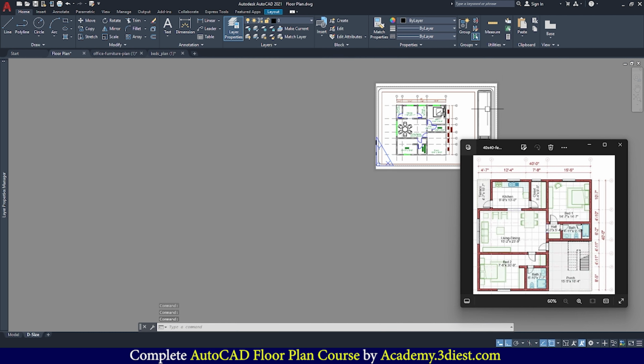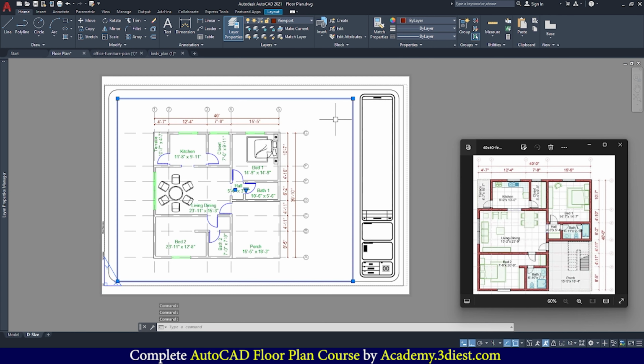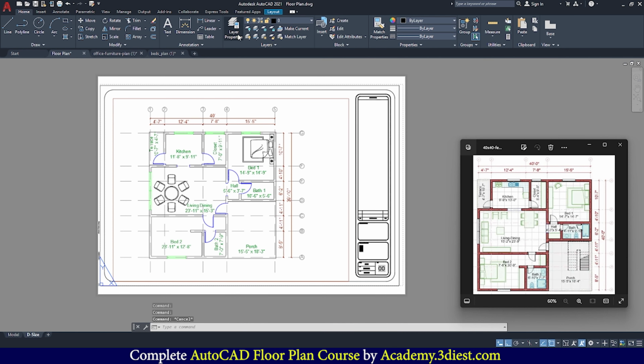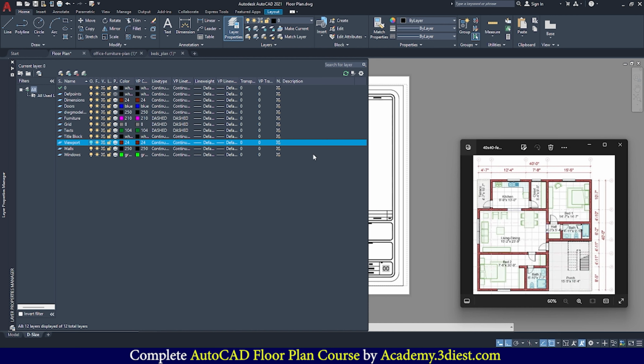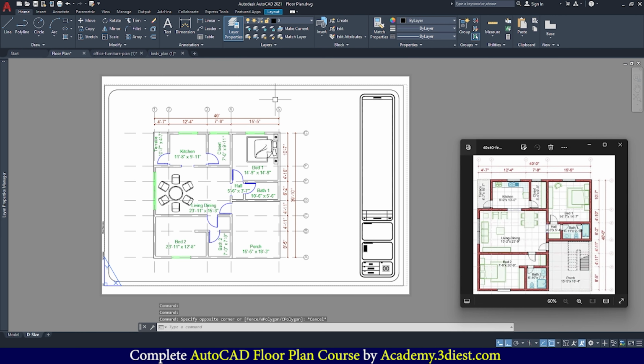Then, as you can see, this viewport we had assigned to the viewport layer. Now I will launch my layer properties panel and turn off that viewport layer. Because of that, the border that we were able to see for the viewport is getting hidden, and that's what we wanted. That's why we hid only that viewport layer, and because of that the views are still available, only the border for the viewport just got hidden, as we don't need that area over here. So it's completely fine.